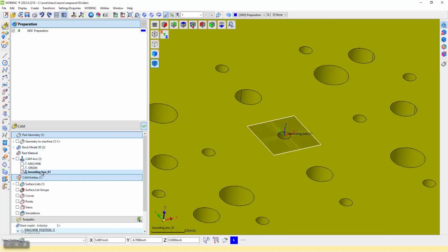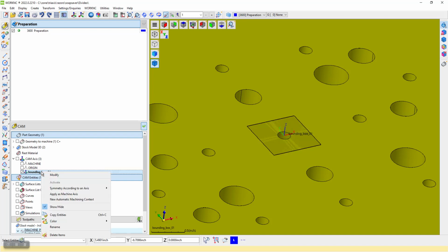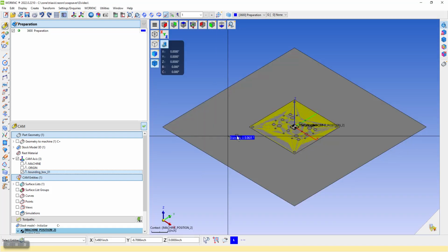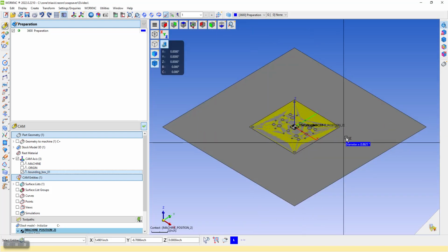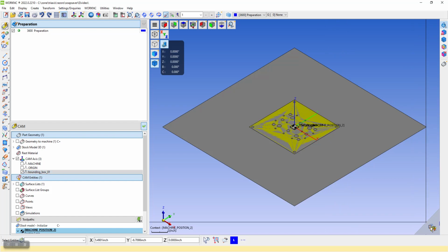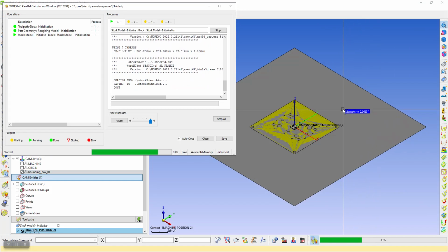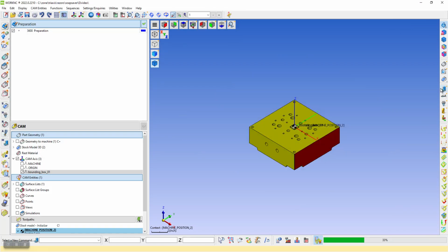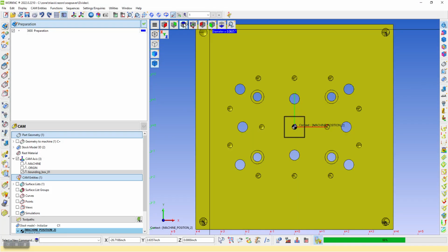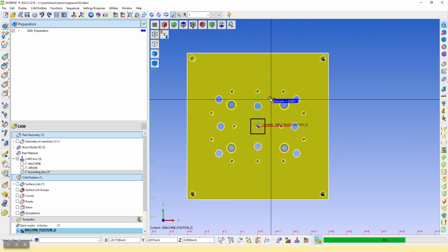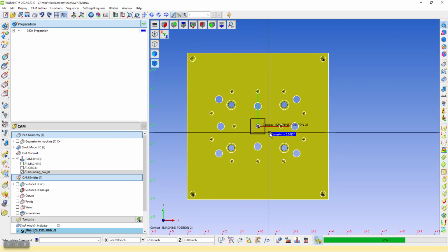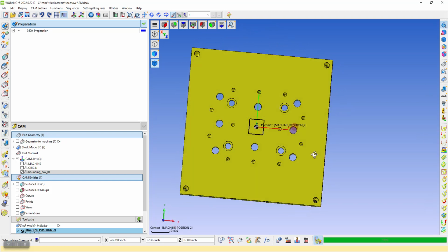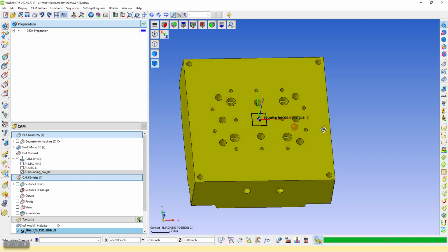And once that's set, you'll right click one more time and hit apply as the machining axis and hit validate, and it'll show a little gray halo of where the machine would be, and I'll right click on there to process that out. And to get rid of this gray sheet body, I'll just click on this machine button right there. And I'll go to top view again, snap that back into where I'm looking at it. I'll hold the shift button down and right click, and I can rotate around without having to click on any rotate tools, kind of get a good look at what I'm working with.